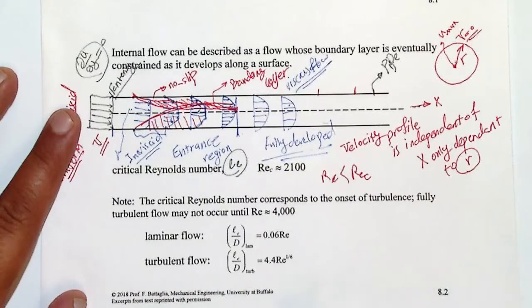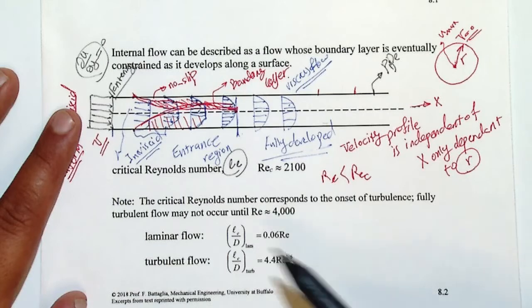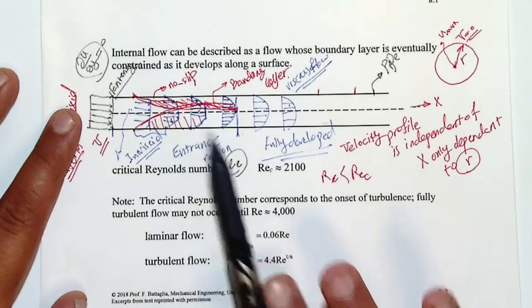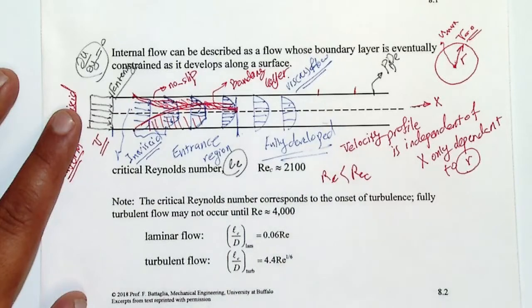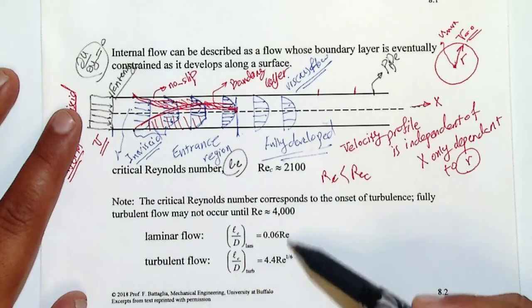Okay, so that's why, again, laminar flow and turbulent flow are totally different, and the equation for each is also totally different. In the transition region you have a transitional period, because you are moving from a uniform flow to fully chaotic flow. Then it's going to have an entrance region that changes like this one, and after that you have fully chaotic, or fully turbulent, flow. In both of them you can find the entrance region, and for these two it can be found by two equations, both related to the Reynolds number.